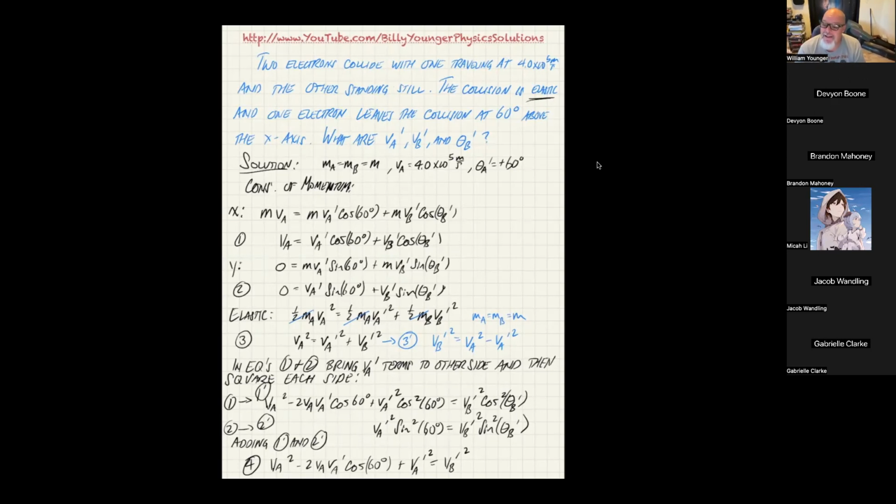Yeah, so VA is the hypotenuse of VA prime plus VB prime. So that at least is a heuristic argument that VA and VB being perpendicular, or VA prime and VB prime being perpendicular to each other, is consistent with the elasticity equation. So that is more or less how you lock it down.